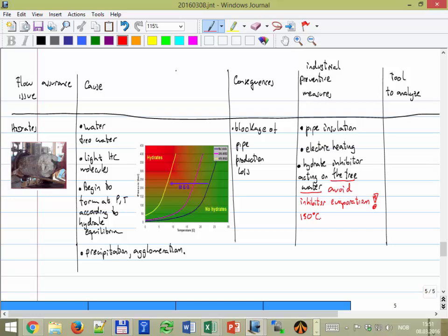Yep. In compressors, we usually don't want the liquid fraction. Yep. But we have wet gas compressions, for example. There are now a lot of, for example, in Snohvit, they are going to install a wet gas compressor in 2020. It's already in place in Gullfaks. So there is a technology to compress liquid multiphase mixtures. Okay. So it's actually compressing.